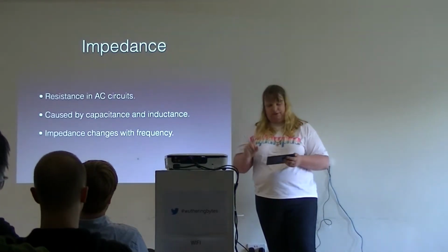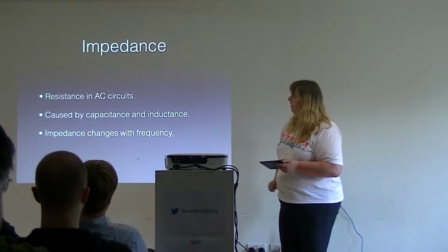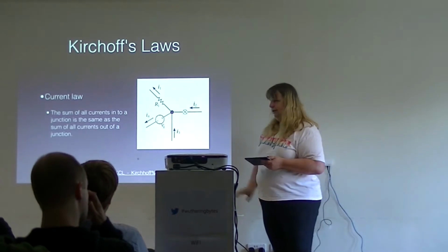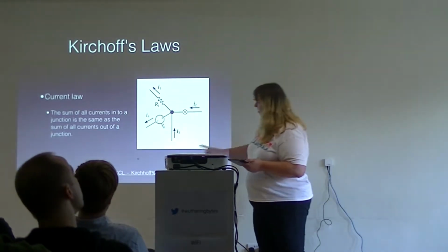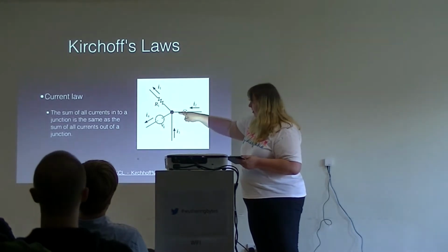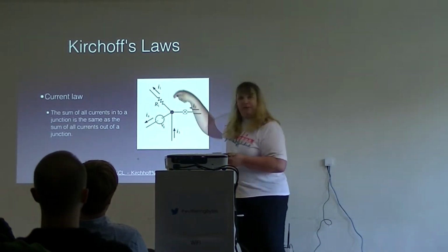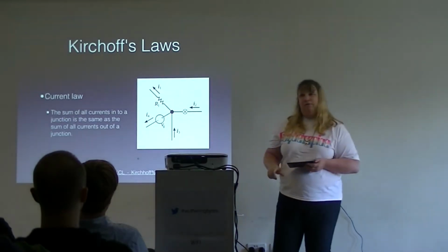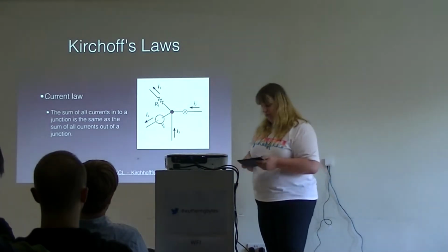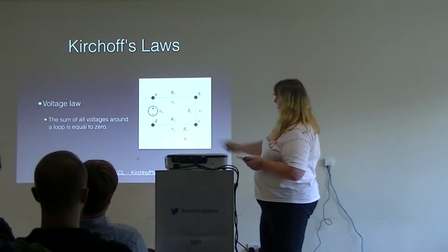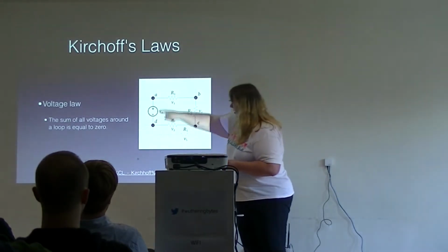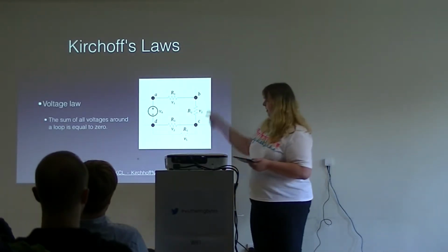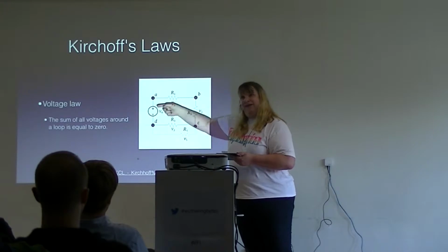So, the only two bits of physics in the talk is this guy, Kirchhoff, and he has two laws. And you can remember, it's basically all current going into that point added together is the same as all current coming out of that point. So it balances. And he did another one, which is the voltage law or the loop law, which is that if we've got that as a battery, that voltage plus that voltage plus that voltage plus that voltage comes to zero, because in some cases it's going backwards, so it's going to be negative.